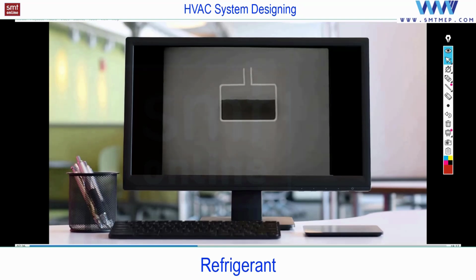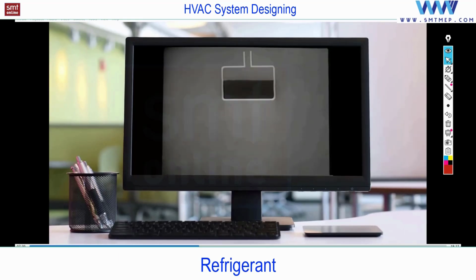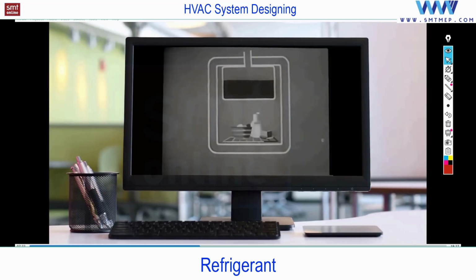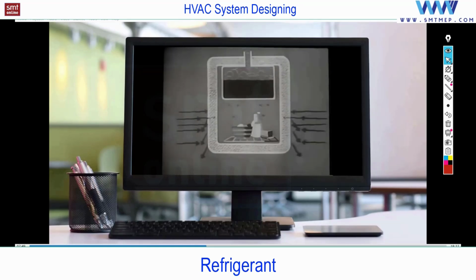Refrigeration would be adequately achieved if we placed a liquid refrigerant in a box and provided an outlet for its escape following its change to a gas. However, at this point, several practical problems must be solved. To minimize the amount of outside heat that enters the refrigerated storage space, the walls of the box are filled with insulating material which does not absorb heat readily and is a poor heat conductor.